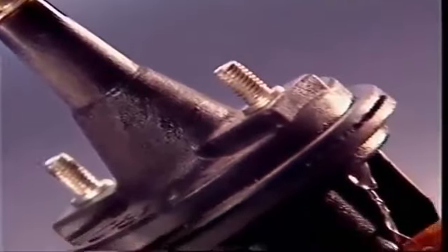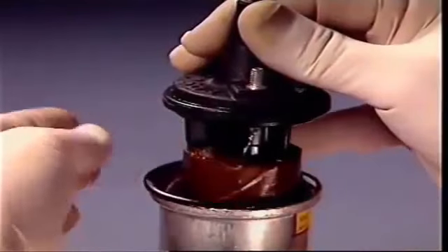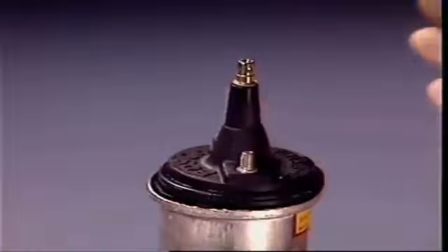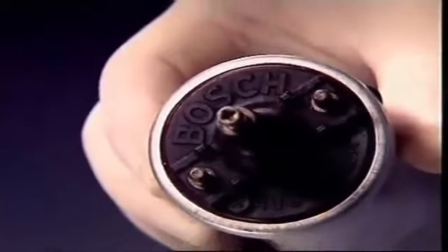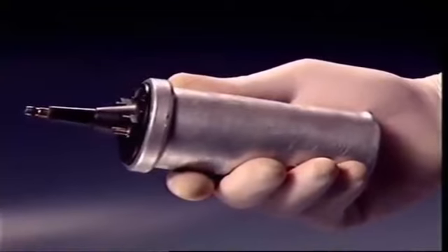One end of the secondary winding is connected to this center terminal, and the other end is connected to one end of the primary winding. A rubber seal and a molded insulated cap seal the assembly in the container, and the container edges are swaged over to bind the coil into a compact, vibration-free unit.